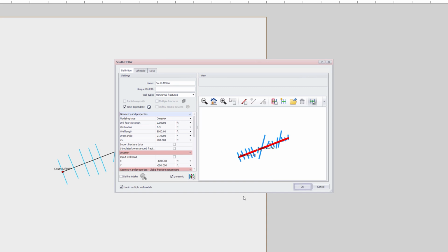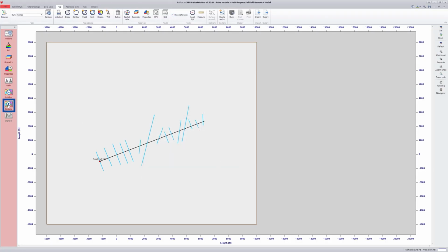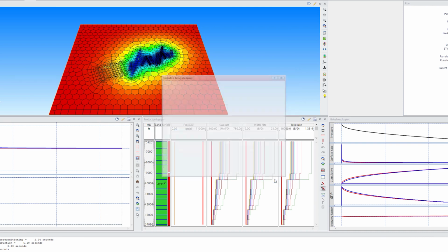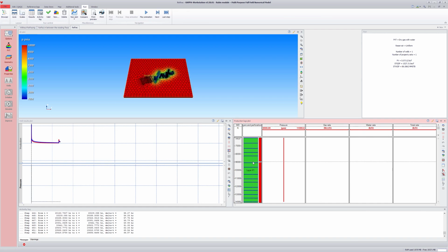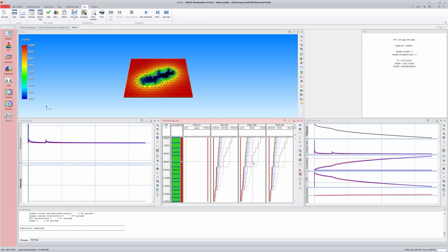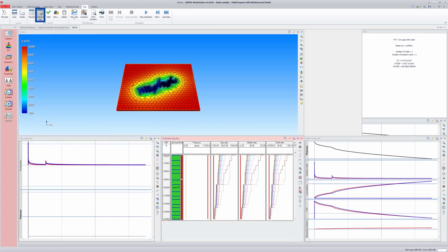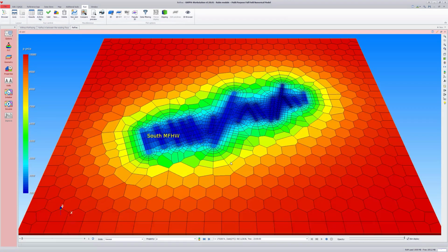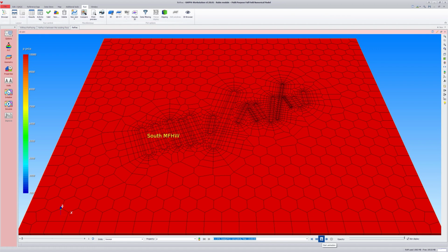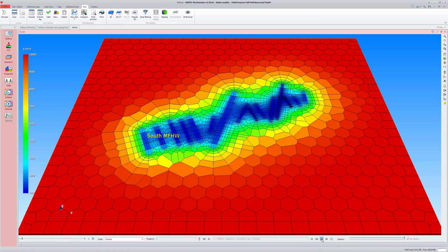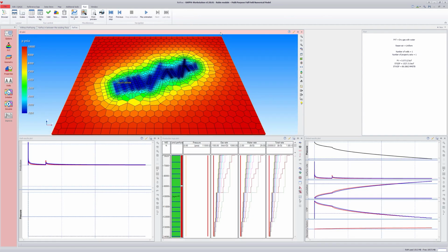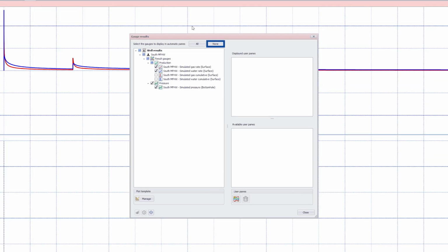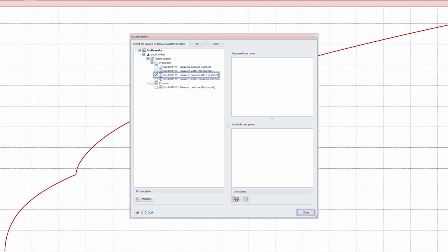Under the Run tab, the simulation is run again. Once the simulation is complete, in the maximized 3D plot, the pressure fields are played back, one step at a time. After 3 years, the other fracs also start to contribute. The 3D plot is restored, and the well results plot is maximized to display only the cumulative gas production.